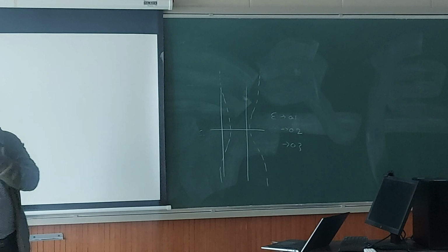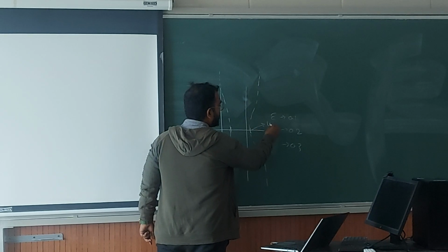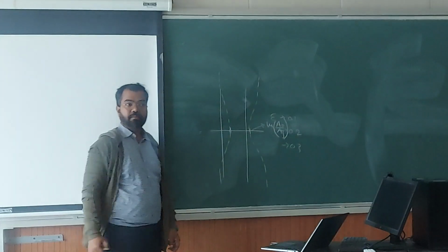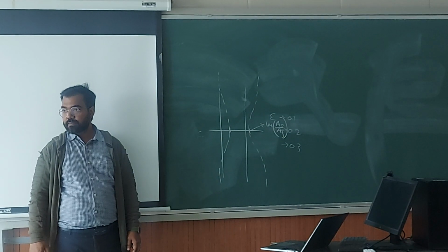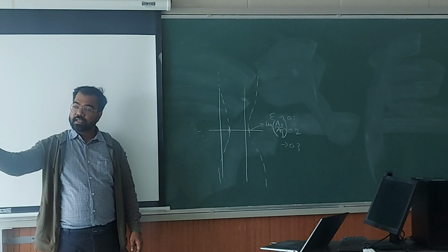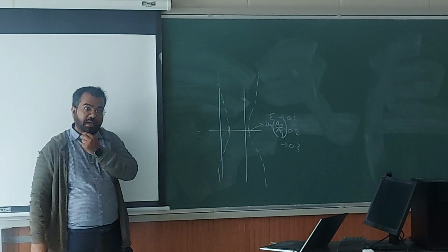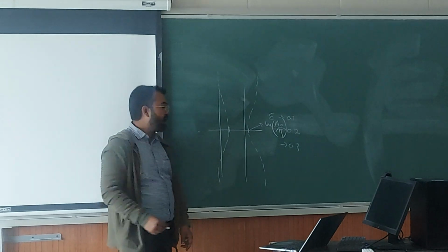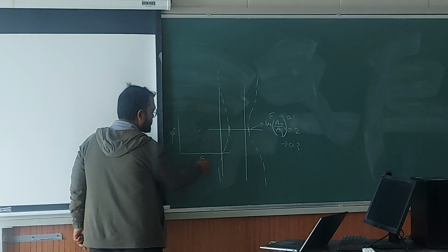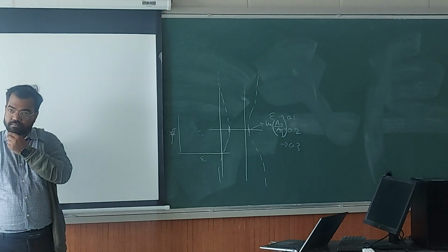Okay? So by measuring the area here, how much area reduction has happened, you can find out the value of strain there. And for that amount of strain, how much void volume fraction you had, you can see under a scanning electron microscope. By doing it for 10, 20 specimens, you will have kinetics of strain versus void volume fraction. So you can plot F versus epsilon, and this should be the kinetics of omega.